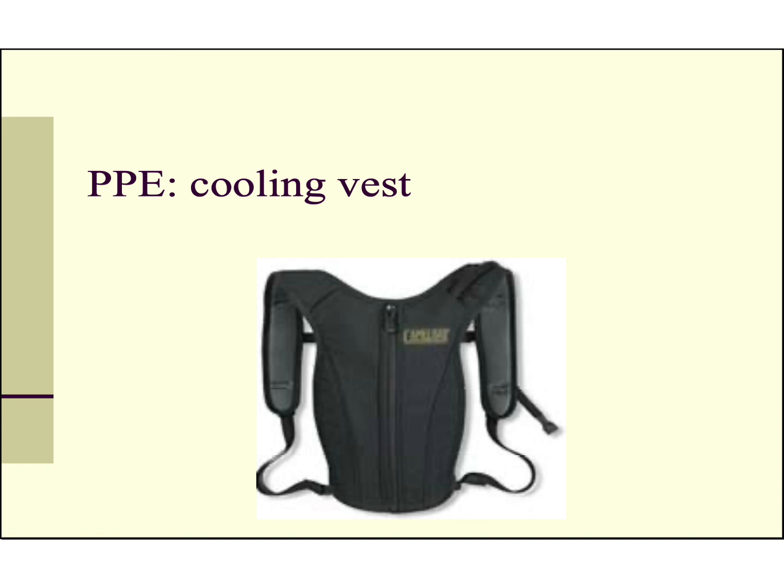Here's an example of a personal protective piece of equipment, a cooling vest that has space in it to put ice or real cold water, or sometimes they even use dry ice. These may work for a period of an hour or up to a few hours. There are also helmets that have ice in them or that can circulate cold water in them to help with very stressful conditions where a person can't simply use the work rest schedules.